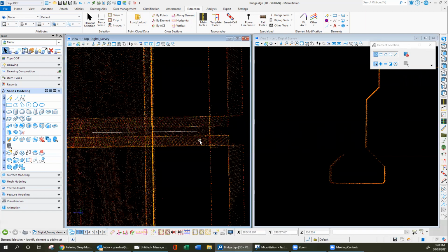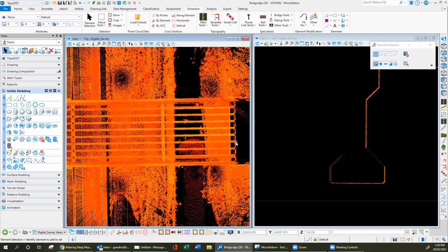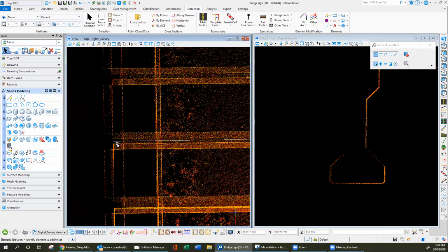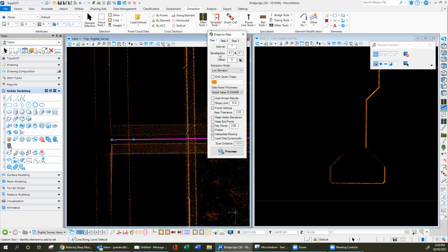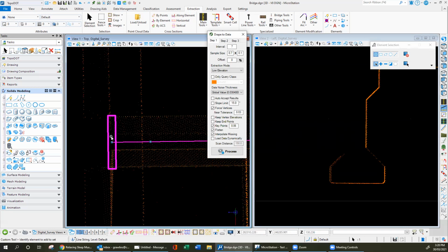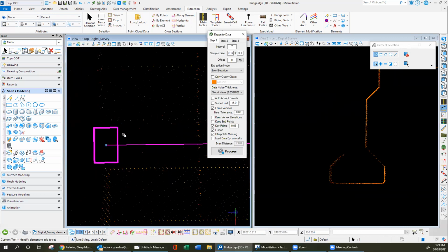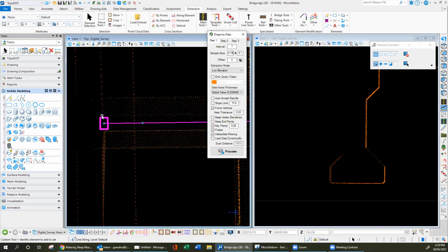The next step for us is to go ahead and drape this. Okay, so let's go up to this other end here. Select it and grab the draping tool. Now we've got some options here of what we want to do. We could either choose to drape it considering all of the points for the full width of the concrete beam, or we could just consider them just for the inner section. So we might go with this inside only and ignore all of the points on the outside of the beam, just in case the beam is slightly skewed over. So we'll go with that.